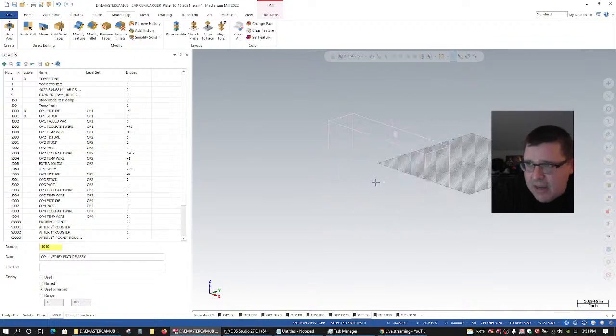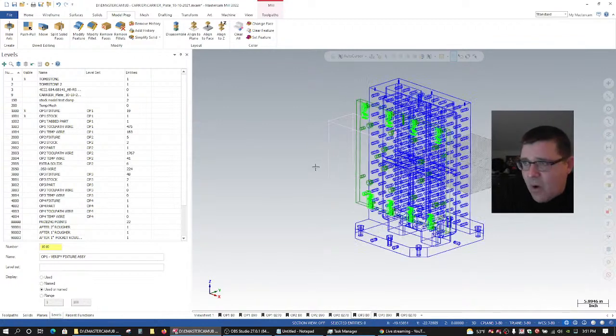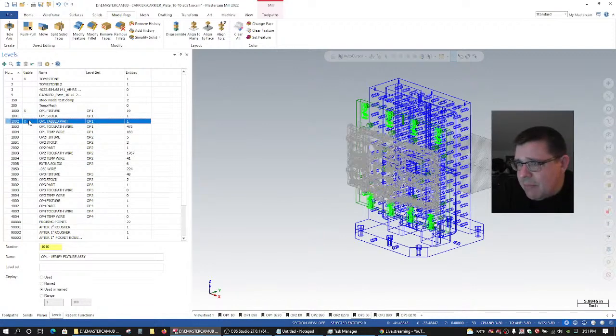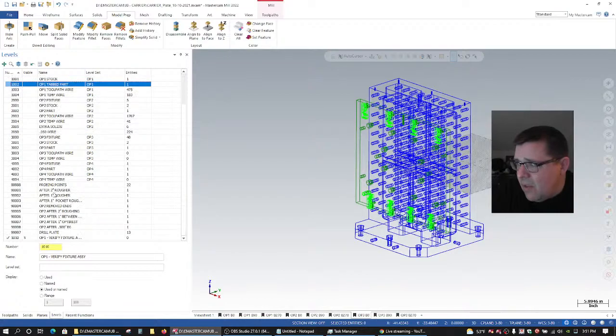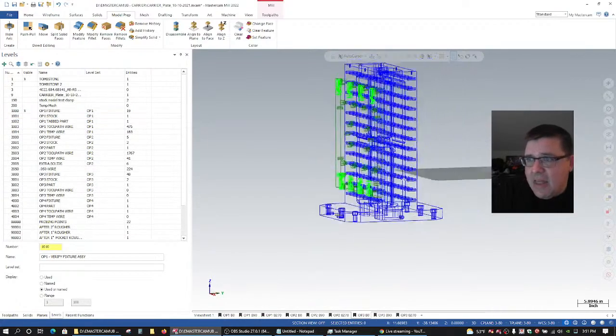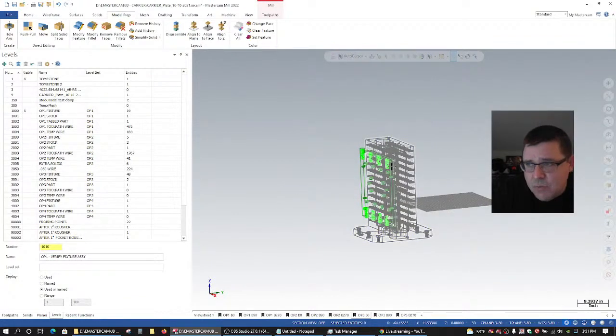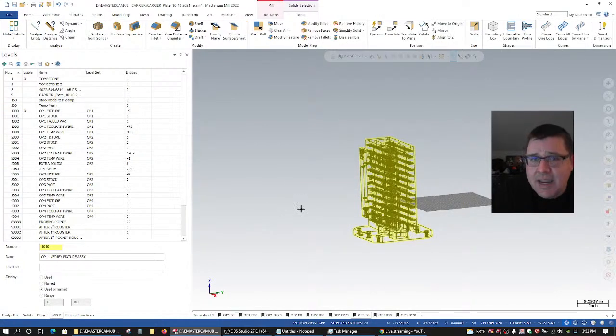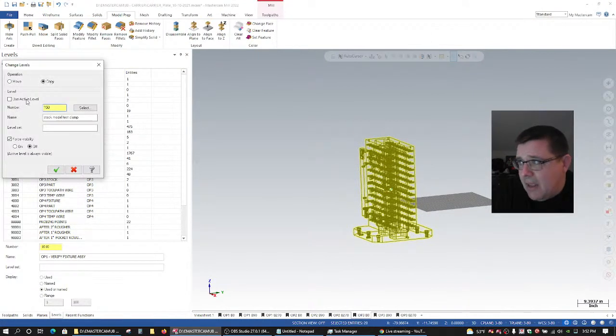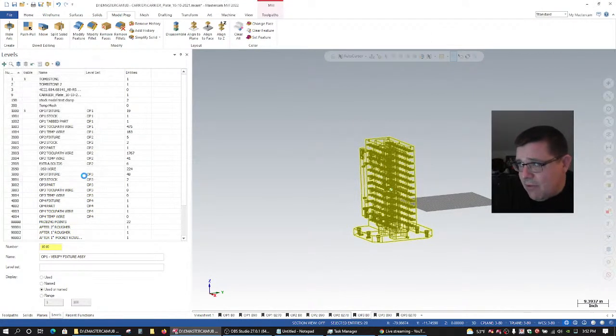My stock's already there, and it looks good, and it's got a hole in it. So if I shade that, it's got this lifting ring hole, but that's not so big a deal. I'm not going to worry about that. So tabbed part is my finished part. Basically, this is all of the data that is going to be my fixture. Each piece of these, the tombstone, each clamp, the two pins and the plate, all of that data is going to be my fixture. So I'm just going to copy everything to my active level.